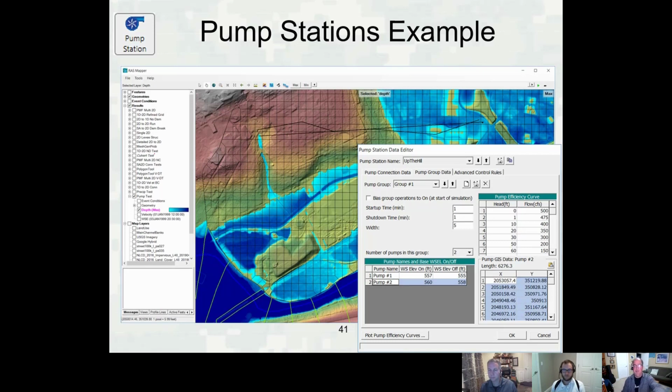And then it's going to give that volume of water over to the other end over the time step. Now, if that volume of water is much bigger than the volume of water in a cell, it's going to drop the water surface of the cell. But remember, there's still water coming into the cell over that time also. So depending upon how efficient it is at pulling water in, it may not completely go dry. Okay. But it might bounce too much.